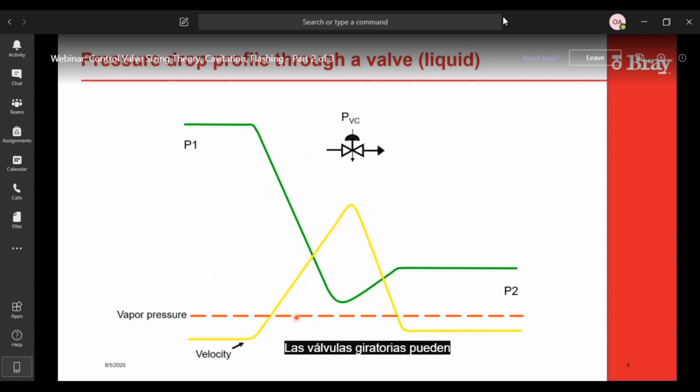Rotary valves, there can be two turns, and that's why when the valves are closer to being closed, they have a higher recovery factor, because the fluid has to turn to get out of the valve. Whereas when they get further open, there's more of a streamlined shot for the fluid downstream, and that's where they get the higher velocity potential. Got it.